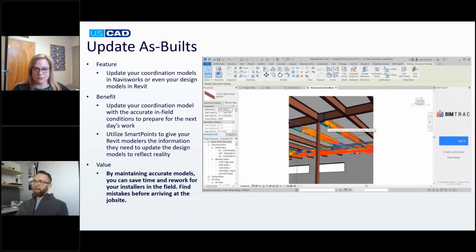Yeah, and I think the real benefit here is it's taking the point cloud data, we're comparing it where it's out of tolerance, and then it's actually pushing the updates of the real-world conditions back into the Navis model. So the manual drag and drop of the Navis model, where you've had to manually adjust things based on the field verification, all of that can now be automated, to Linda's point, through the plugin, making it super simple for you to jump in and actually take the functioning content in that model and make it easier to interact with.